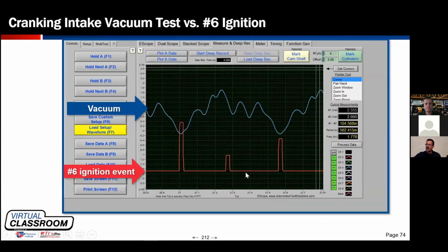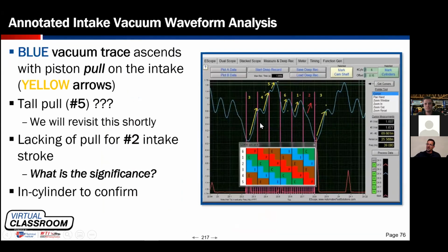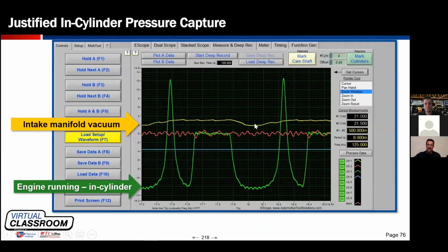How do I know that? Because the waveform tells me the entire story. I know my intake valve is not opening. I don't know if the cam lobe is gone. I don't know if maybe the push rod vanished into thin air, right? But I do know these are common for the threads for the rocker pedestal to rip out of the head. But either way, I know step 1 is going to pull that valve cover off and take a look.